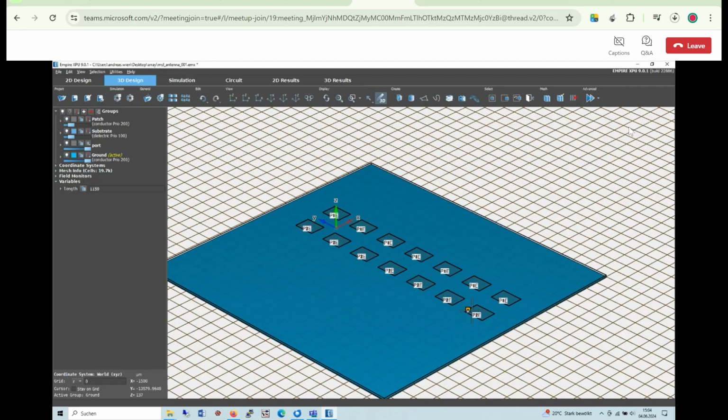So there are two RX channels at the moment for the antennas or for the radar. And my aim is to excite once this column, and in another simulation to excite the lower column, and then evaluate the phase difference of both results. This is my goal here.